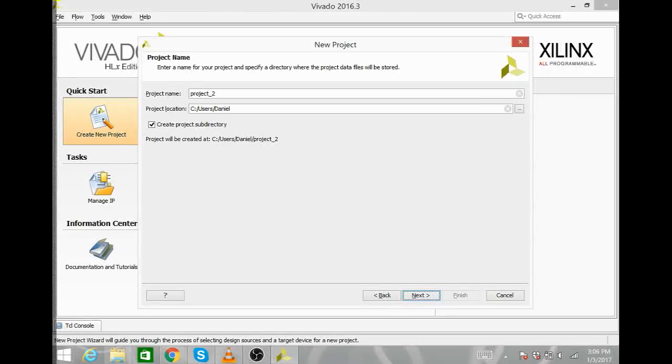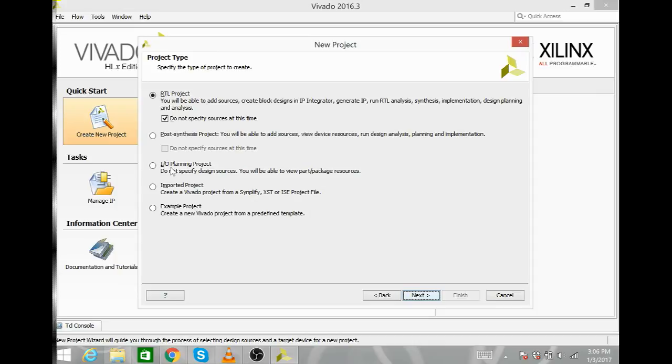This project, I'm going to call it tutorial 1_1. It's going to be an RTL project. We won't specify sources at this time. In future videos I will show you what that means and how to use it. But for now, just click on that.